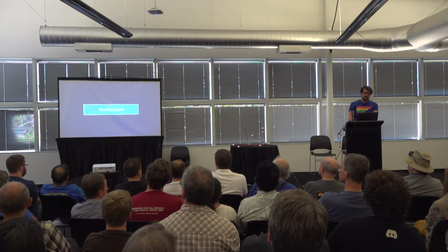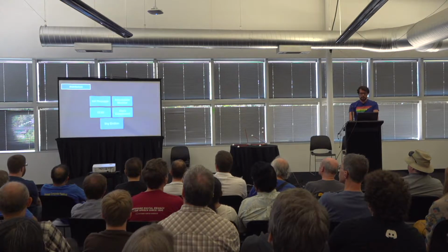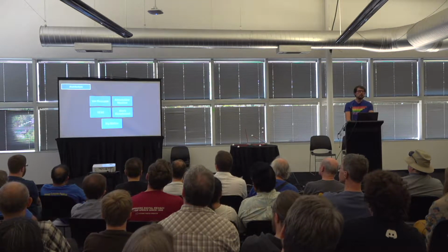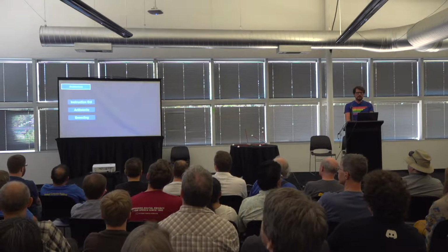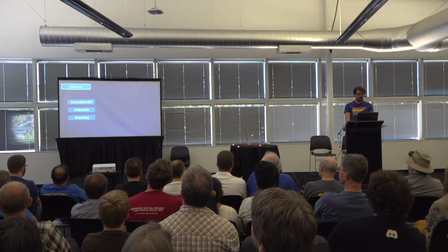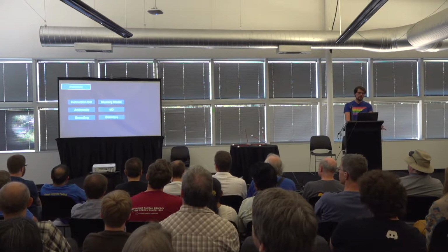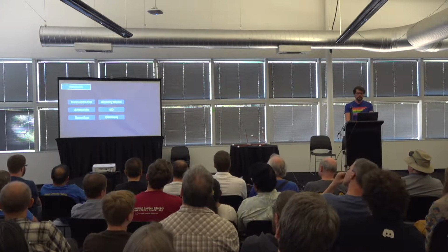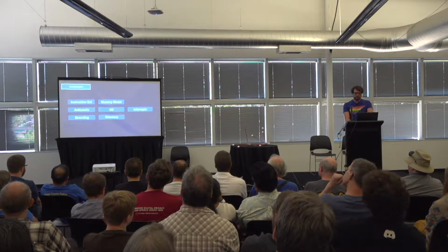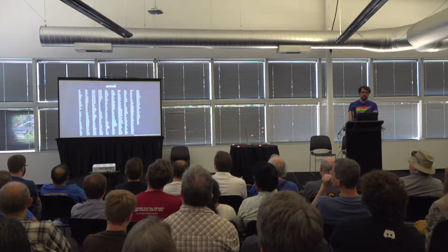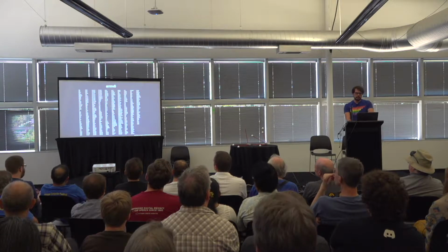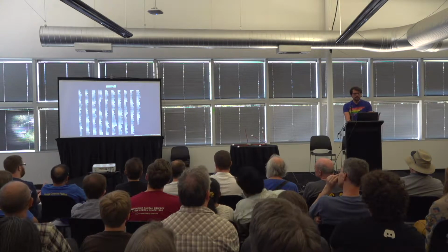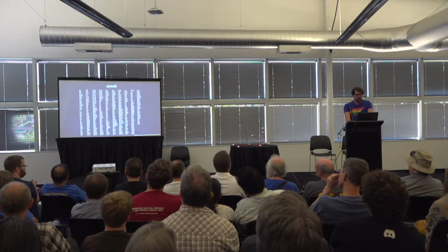The architecture of the AGC CPU can be described as a von Neumann accumulator machine with 15-bit ones complement big Endian arithmetic. So we will talk about the instruction set, the arithmetic model and instruction encoding, as well as the memory model, I/O operations and counters, and finally the interrupt model. Machine code instruction sets vary widely. The instruction set of a modern ARM processor, which is mainly optimized for runtime performance, consists of about 400 instructions.